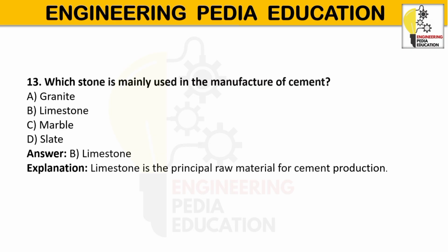Its percentage is 60 to 65. Proper amount of lime increases strength and ensures soundness. If it is in excess, expansion and unsoundness form, and cracking occurs. If it is deficient, it reduces strength. Cement sets quickly and becomes weak.